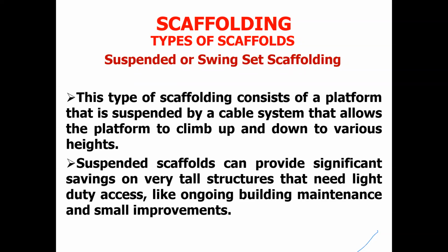So what kind of scaffold are you going to use to get to that height to be able to do that? And that is where the suspended or swing set scaffolding comes in. And on most of these high-rise buildings, they are pre-installed as part of the building elements, and they are called cleaning cradle.